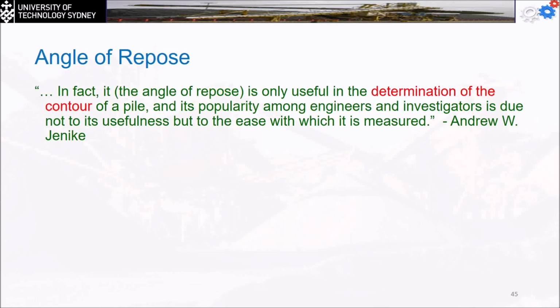Does anyone here have any experience with construction or civil engineering? They have something similar, though it's quite different, but it's going to be useful for you in the future. Usually, if you bring concrete by mixer, you should not leave it more than 50 minutes in the mixer, because this will change the parameters and characteristics of the concrete.